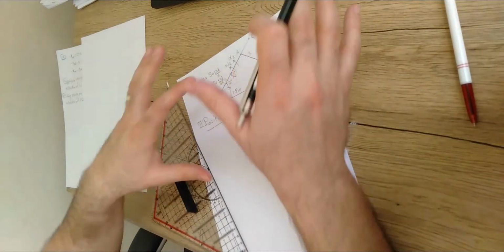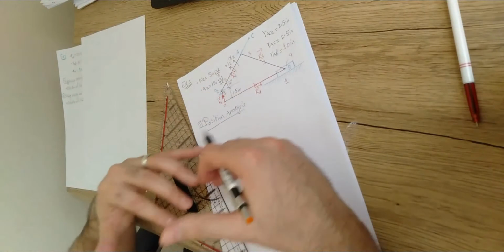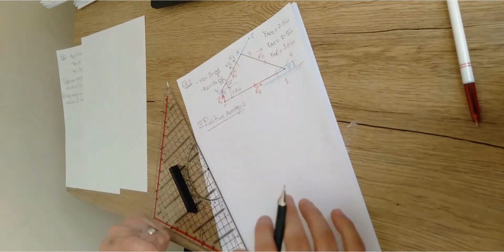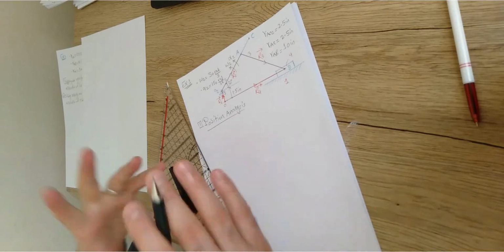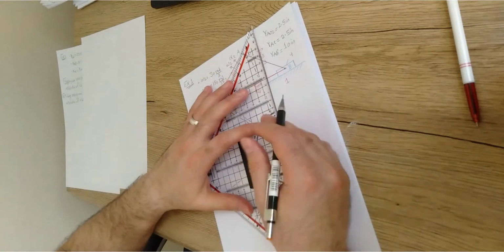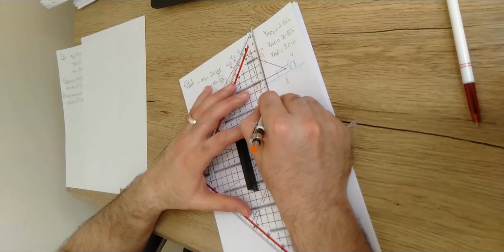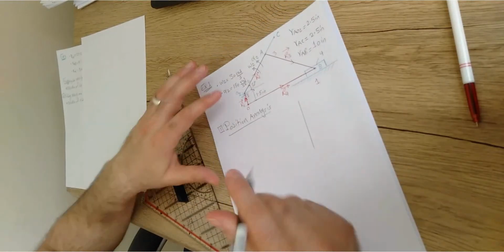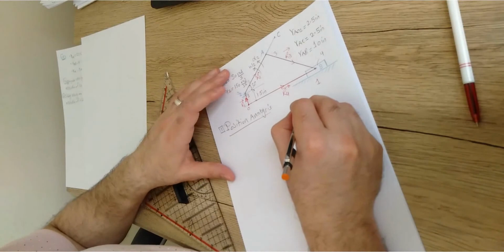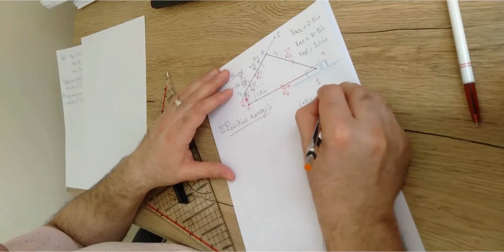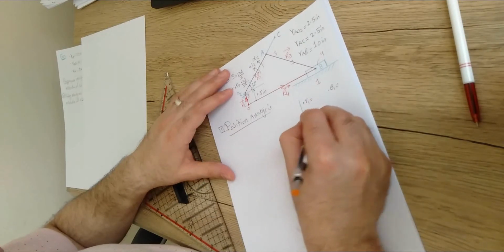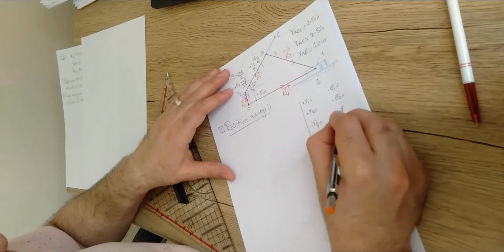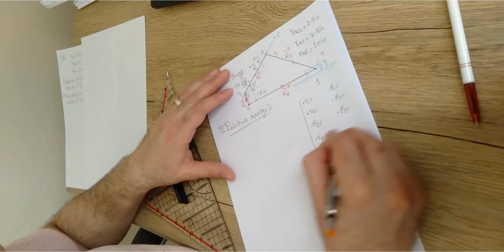You can work over this given problem, or you can redraw the mechanism again and allocate and define all of these different position vectors. It doesn't matter whether you redraw it or use the same drawing that is already given to you. Anyway, your objective is just to specify the given data, which is given and which is unknown, in terms of R1, theta 1, R2, theta 2, and in addition R3, theta 3, and R4, theta 4.